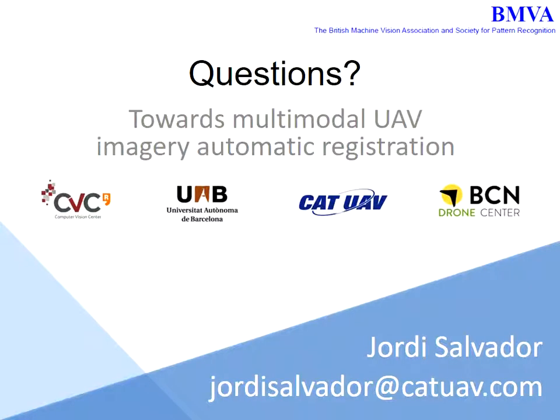It is not really clear to me, this error investigation you made. You compared a photo from a camera with central perspective, a photo from the UAV, with an orthophoto, which has a parallel projection. So the question comes up: the errors that you have come from considering the terrain model in the orthophoto or not, but not from the camera or from the matching. Could you explain how you make this error investigation without creating an orthophoto from the UAV? So it makes, from my point of view, no sense.